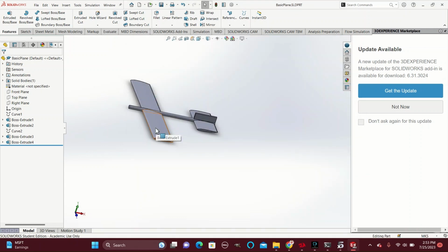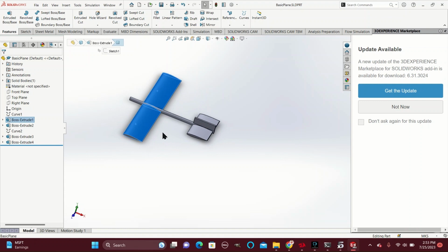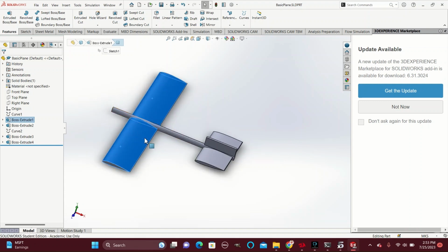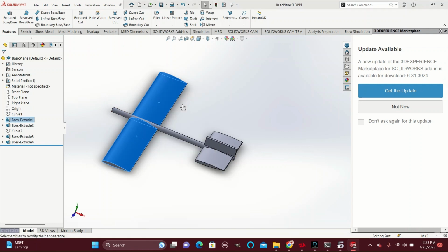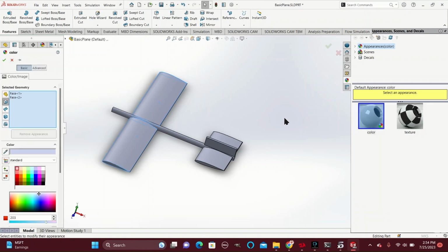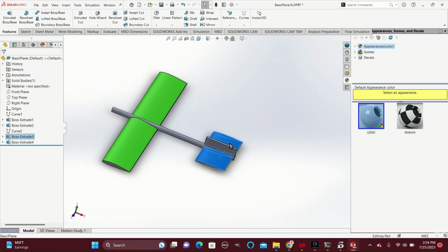And if you want to do more to make your model visually distinct and change how it appears in various load-ups, you can select both of these. Make sure to hold control when selecting the second one, go to Appearance, select Face 1, and then you can select a color for your wing section. And repeat the process over here. Select Face.